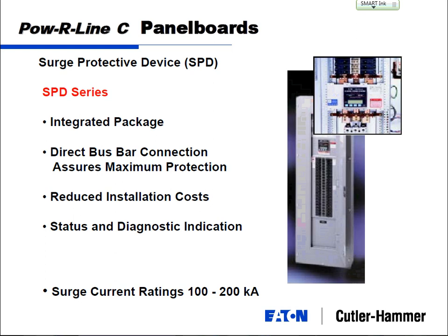And we always believe in the cascaded approach, so if you're designing a building from scratch, always put one of these on your service entrance piece of equipment so you can have that first stand of protection against lightning strike. The next step is to always do a second layer, a cascaded approach, and that second layer, depending on the type of facility, could be in this panel board or the critical panel board of your loads.